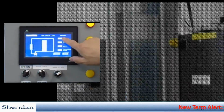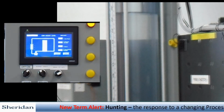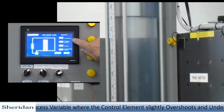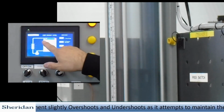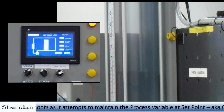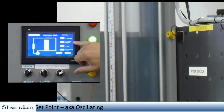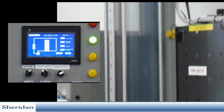So what we want to do is plug in a new number, and we're going to watch the screen, and then you will verify that you're actually getting the correct amount of water column. If you have not calibrated it correctly, you're on your own. Okay, so let's start off. What you're going to do is go to the set point. It's actually not only a display but a push button. It'll come up with a small menu. So we're going to type in 15, enter, and the motor's turning to pump. I see water filling in. And now it's going to try to maintain that 15%. This value will shift between 13 and 14% as it tries to maintain that.